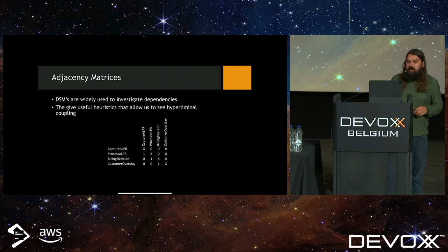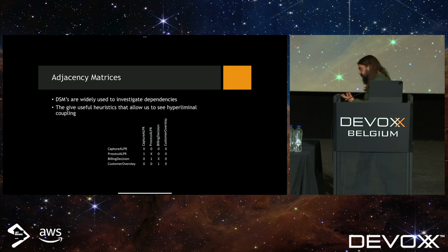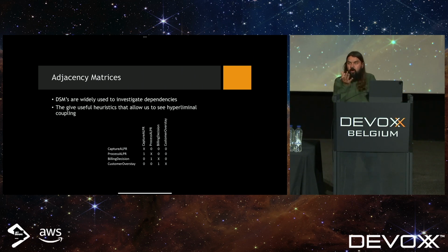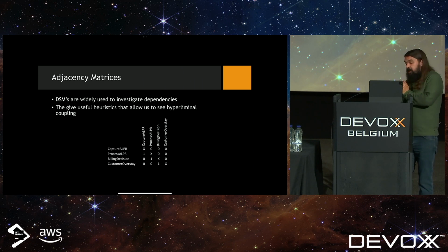The first thing we use are DSMs, or design structure matrices, and this is a tool that they teach at MIT to people who build aeroplanes and spaceships to decide on component structure inside those things. And we look for patterns, and we just map functions, potential components against each other, and we put a 1 where there's a dependency and a 0 where there isn't.